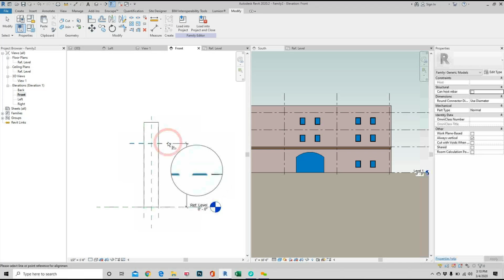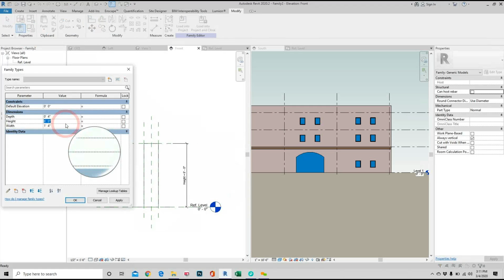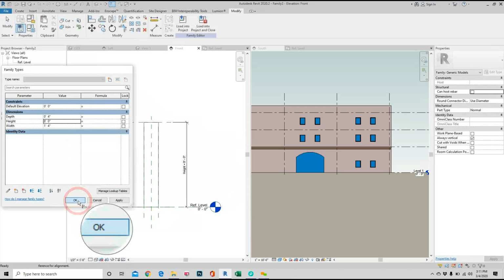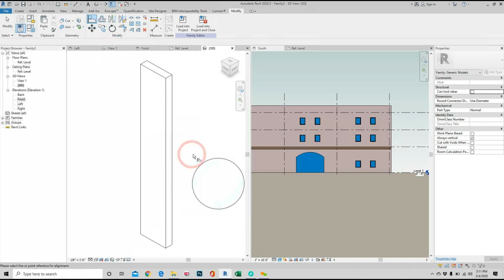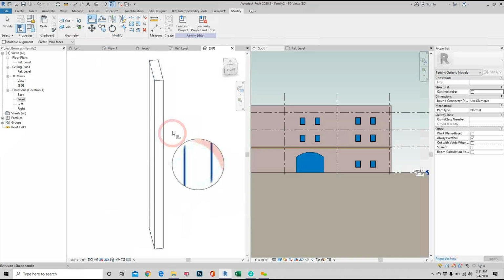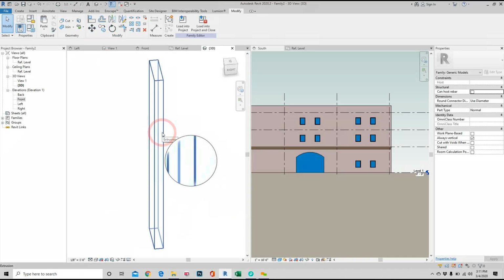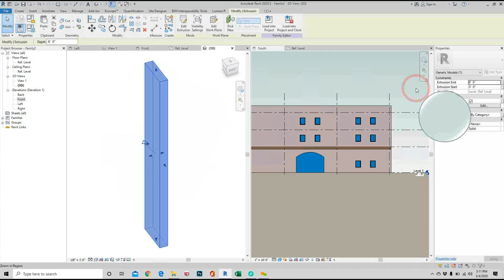And now I can align this to that and lock it. So if I move this, it should move my pilaster. Perfect. All right. So if I go to 3D, looks like this. Nothing exciting, right? But I can go now. Before I leave, let's go ahead and put a material parameter. If I load this into Revit, Revit doesn't know what it is. Okay, so let's go ahead and click on that. And on the properties, there is my material.